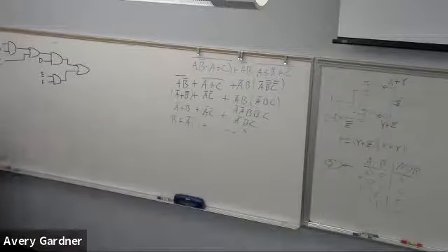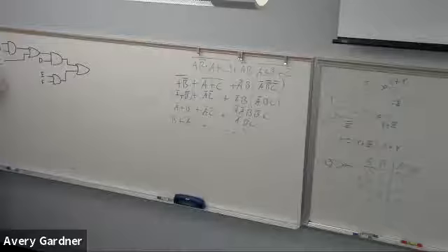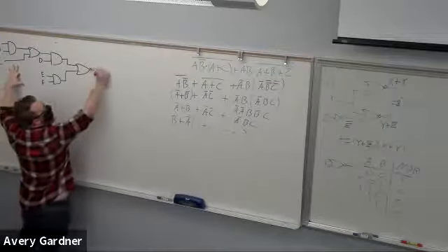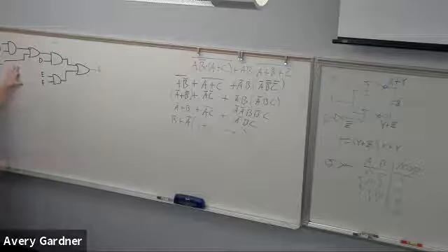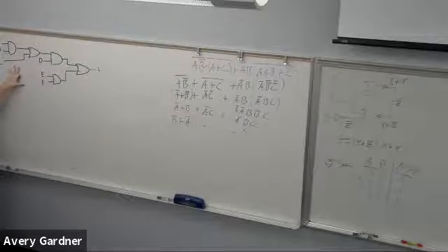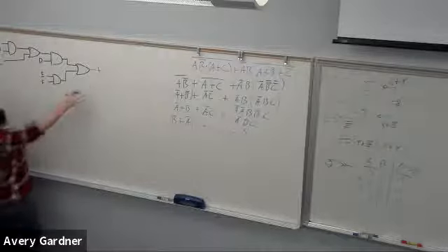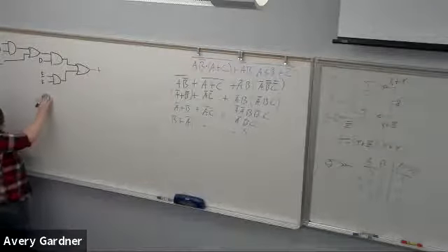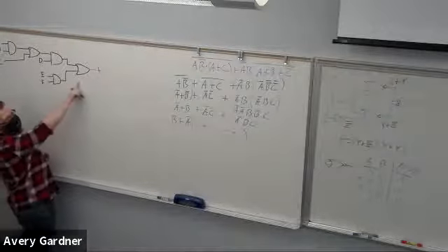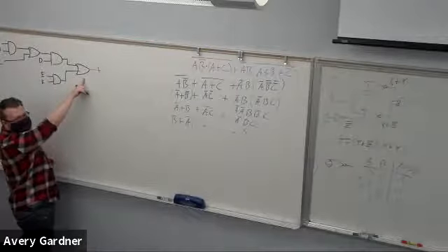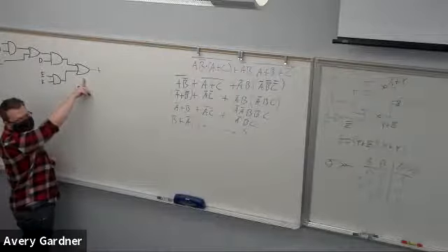Okay, so take a moment, use this one. It's going to be a little bit different, and you're going to have to add at least one gate for this, and you'll find out why. So start from right to left and go for NAND gates. If the output ends up being an OR gate, you're doing a NAND gate design.